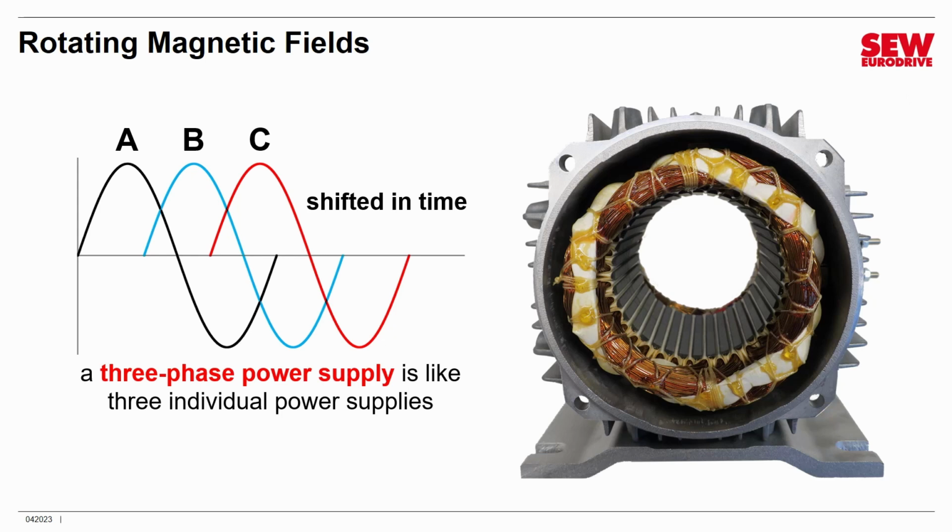The advantage of 3-phase power is it lets you deliver the maximum amount of energy to the motor. It's just a very efficient way of delivering electrical energy. So what happens is 1 coil in the motor is connected to each phase. So that means you're getting 3 magnetic fields that are varying in strength and polarity over time.